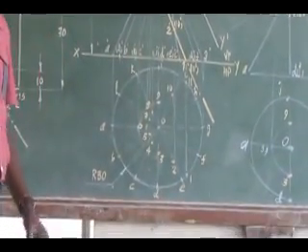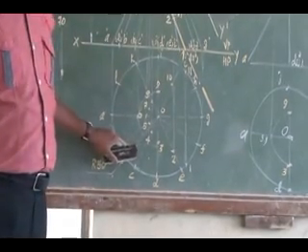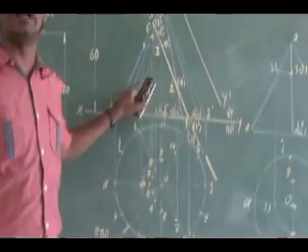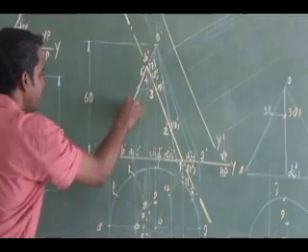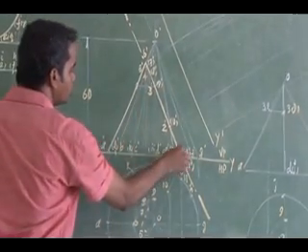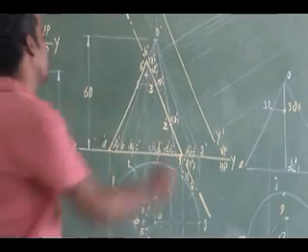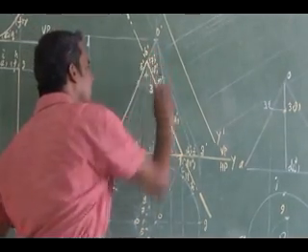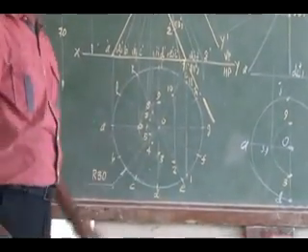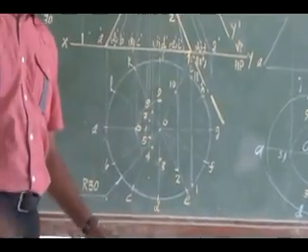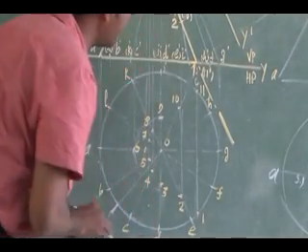By connecting, listen, you have to show the retained front view and the sectional top view. The retained front view is again a triangle. So this is the cutting plane, and the remaining portion of the front view of the cone should be shown like this. Only the extreme generator should be darkened. Then similarly your sectional top view. First of all, connect the cutting points as a curve.